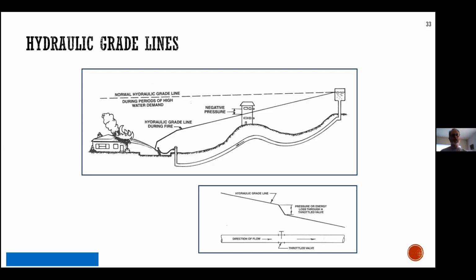Later on in the program, in the weeks ahead, we'll talk about valve maintenance and the importance of recording every time an operator touches a valve. And also making sure that in your utility, your operators are the only ones that are allowed to touch the valve, because contractors or plumbers or homeowners even, with access to a key to close or restrict the flow of a valve, that can create lots of problems, not just for the fire department, but just for the everyday